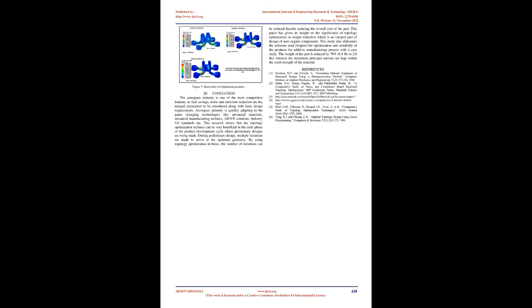The first step in topology optimization is to divide the part into design space and non-design space. Design space is where there is scope for removal of material and optimization. As our recommendation is to use additive manufacturing for manufacturing the redesigned part, there is flexibility to redesign the part without considering the limitations of conventional manufacturing processes. In this case, the bolt holes and the area close to the bolt holes are non-design space as there is no scope for optimization. All the remaining area in the part is design space.